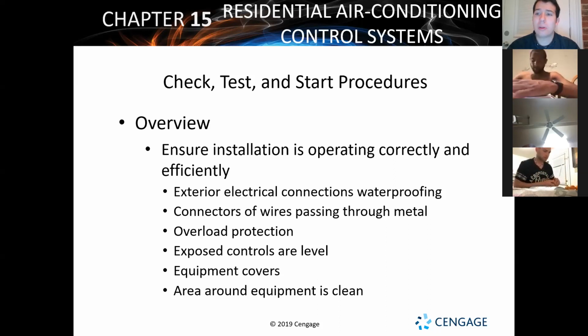And then I've had calls where it could be an appliance that they thought was working and it isn't, like a humidifier. Oh, I got the humidifier wired in, it's good to go, let's get it done. And then the system just never worked because they never wired it in properly.